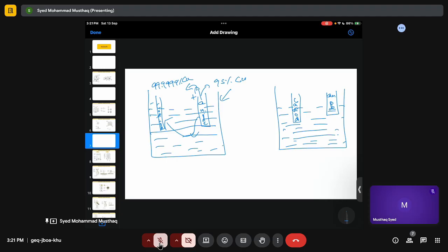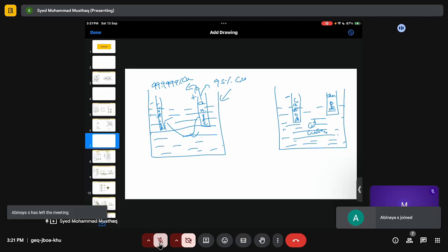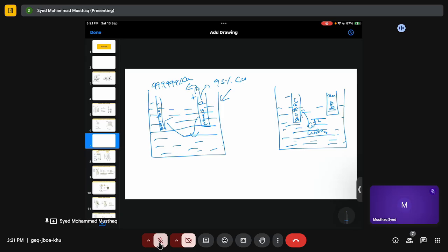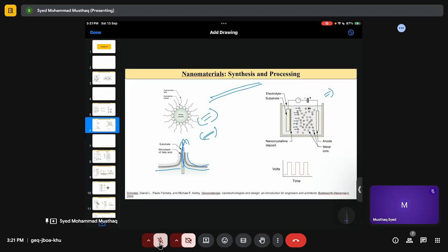And the other way is you have a copper sulfate solution, you dissolve everything into a sulfate solution or any type of solution, nitrate, chloride, and then you apply negative charge here, and whatever copper was dissolved in the solution will get deposited. So the only difference is that in electrodeposition, the ions are coming from the anode. In electrowinning, the ions are coming from the solution. Okay, so that's the only difference. There's no great physics in there. In electrodeposition, it is simple deposition where you take elements from the anode and deposit them on the cathode.